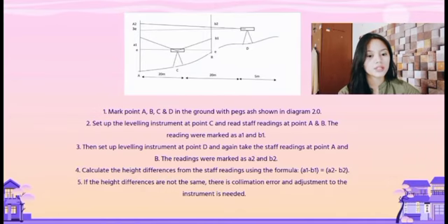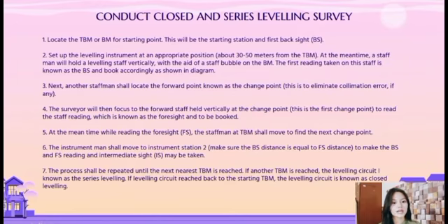If the height differences are not the same, there is collimation error, and adjustment to the instrument is needed. Conduct closed and series leveling survey.